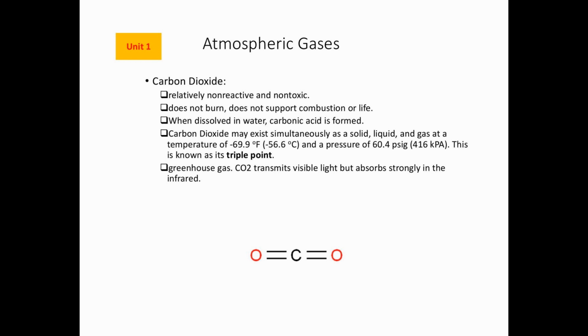Carbon dioxide may exist simultaneously as a solid, liquid, and gas at a temperature of minus 69.9 degrees F and a pressure of 60.4 psig. The solid, liquid, and gas phases coexist. This is called the triple point. It's very interesting, just for CO2.